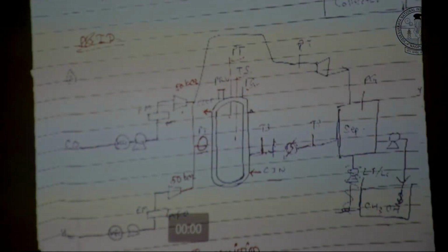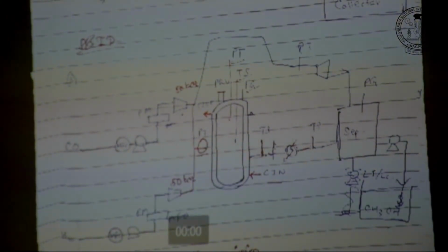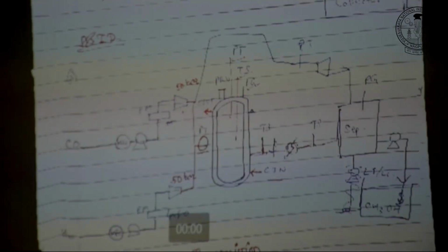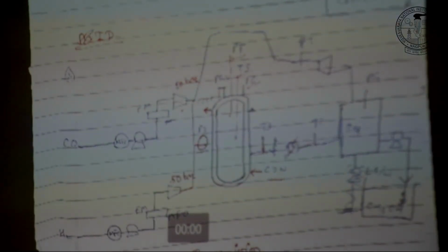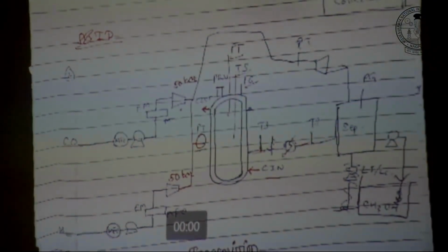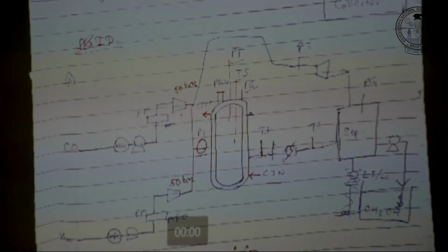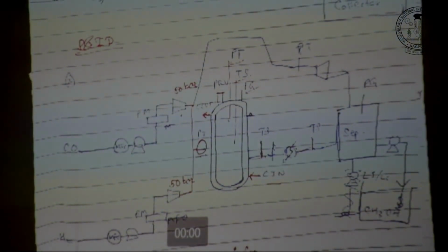So very good. You thought about safety, so a PSV is there. You thought about how you want to operate the plant and what parameters you want to keep an eye on. So PG, not only PT in the control room or SCADA, but you also put a PG. If the operator is walking around in the plant, he is not in front of the control room, even in the field he is aware. So there is a local pressure gauge. Very good thinking.